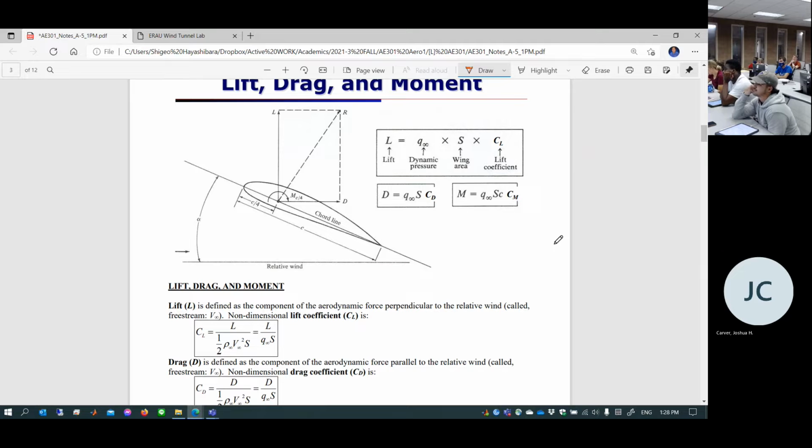You're not even going to talk about pressure, you talk about pressure coefficient. You're not going to talk about friction, it's the skin friction coefficient. You're not going to talk about x distance, you talk about percent chord. What's the location halfway through the chord line? That's called 50% chord, measured from the leading edge. There's no unit associated with it, because it doesn't matter if this is 1 meter, 10 meters or 1 millimeter. 50% chord is 50% chord, regardless of your size.